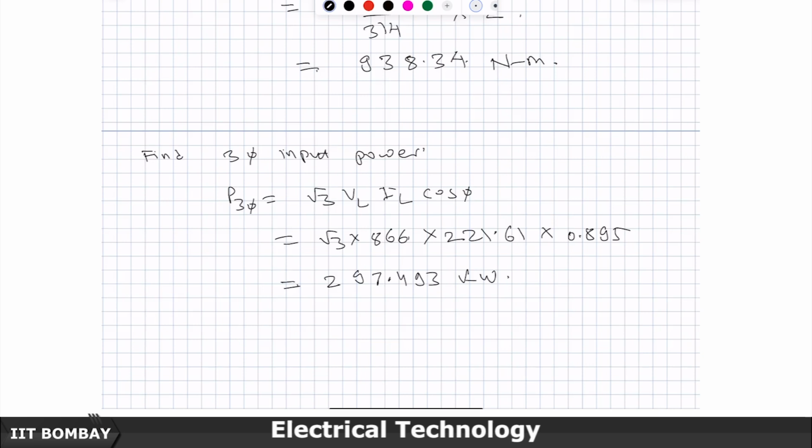So, this is the amount of input power going in, and this 3-phase input power is nothing but what is going into the air gap, because the whole of this goes into the rotor side. So, if you ask me what is the mechanical power, then it is just 1 minus s of it, because I2 square R2 dash, as I explained to you, goes into the loss on a per phase basis, I2 dash square R2 dash by s, and all that.